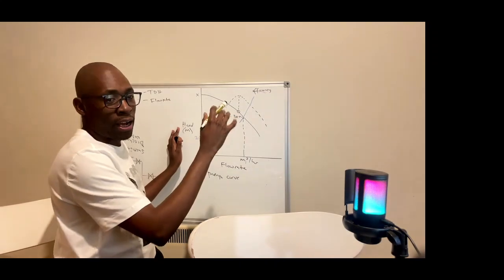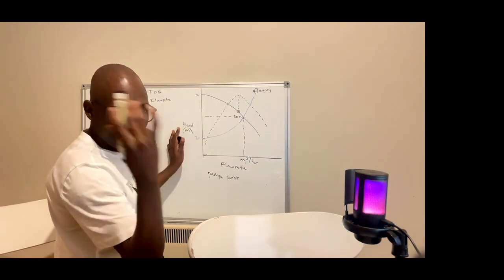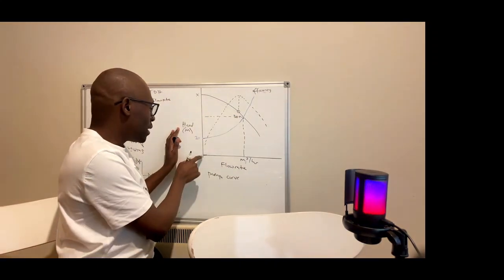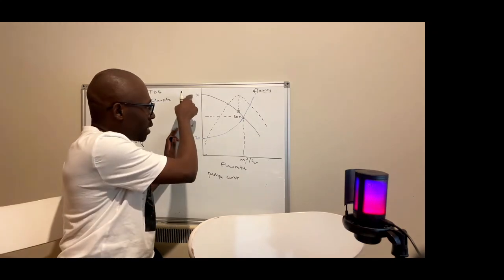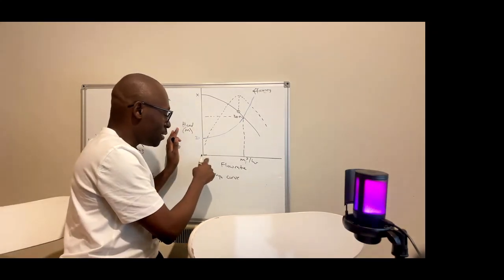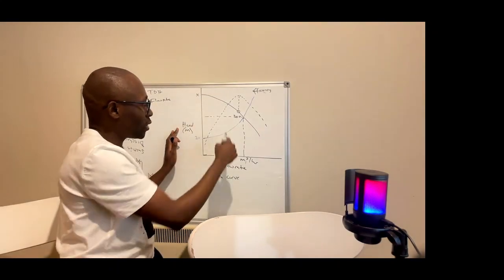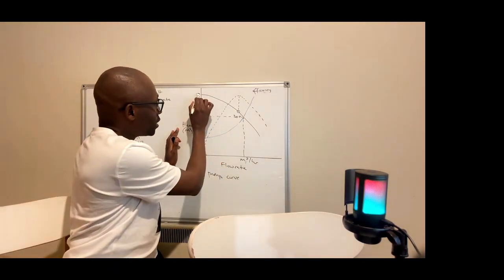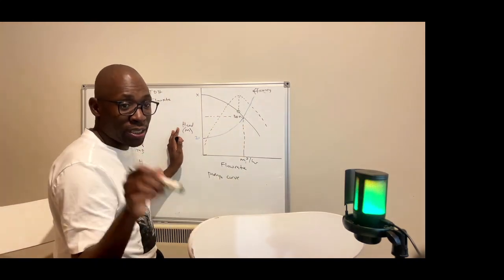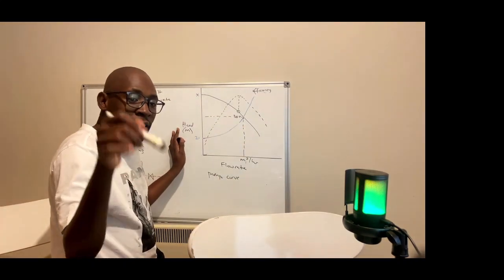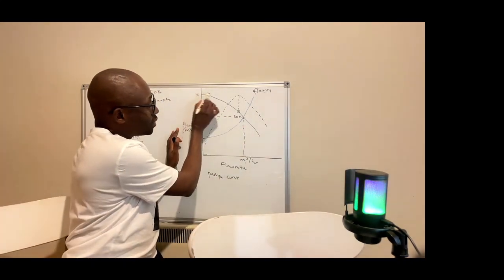It's based on how they have tested their pump to say that, okay, when there is zero flow, what is the maximum head? When the flow is 1, what's the head? Is 2, what's the head? And so forth. Then using that, they plot this pump curve. So it's the manufacturer of the pump that supplies this pump curve.